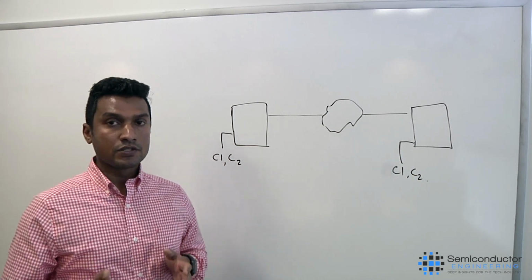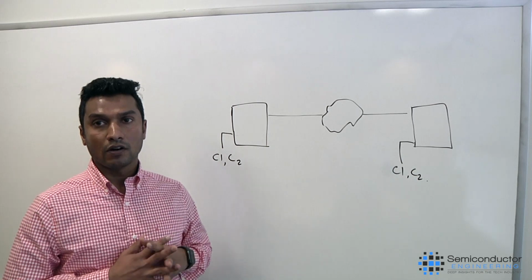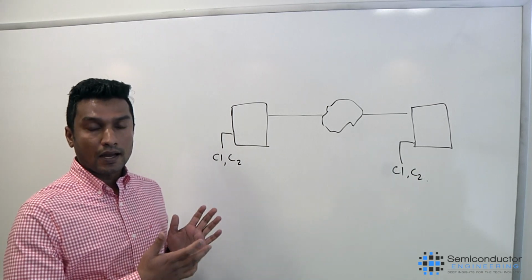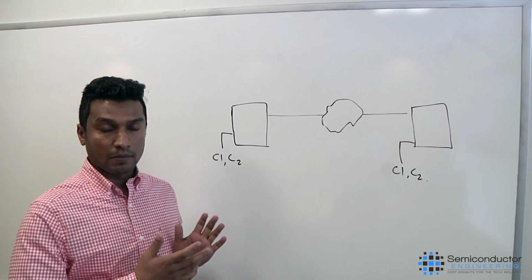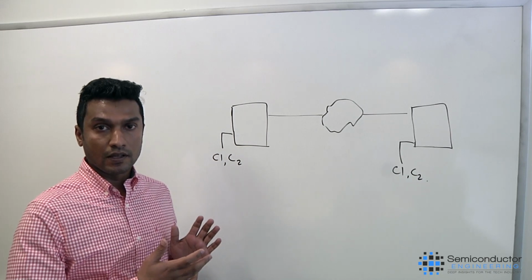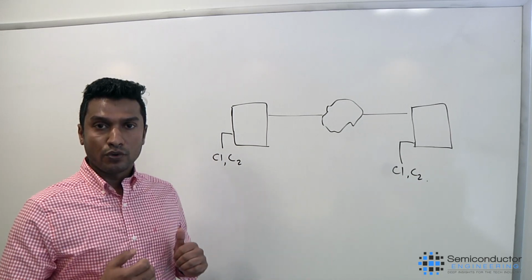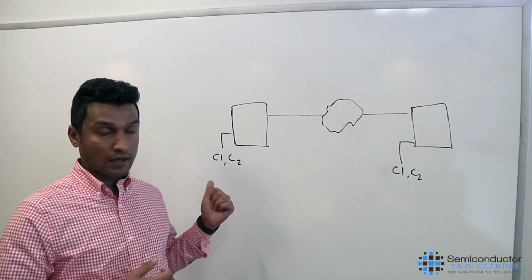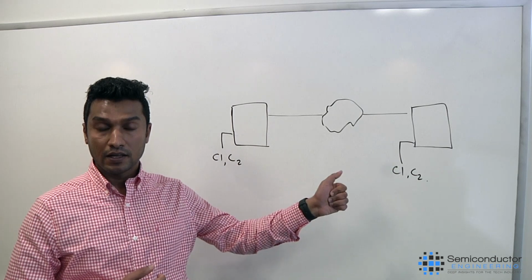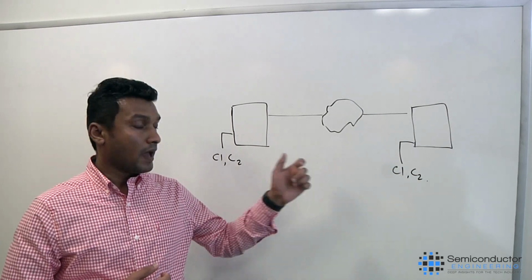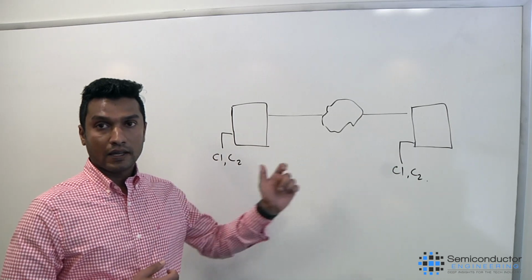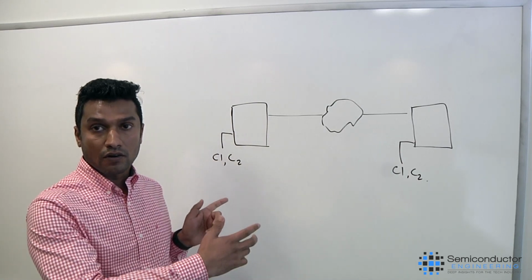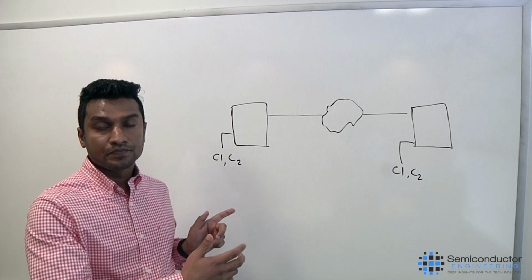Yeah, correct. So these kinds of clock domain crossings you can filter out using that Tcl command that I mentioned previously. What you need to do is get the source, find the source clock, get the sink, find the sink clock, and just check whether the source clock is matching the sink clock, so that you can filter out all these crossings from the design.